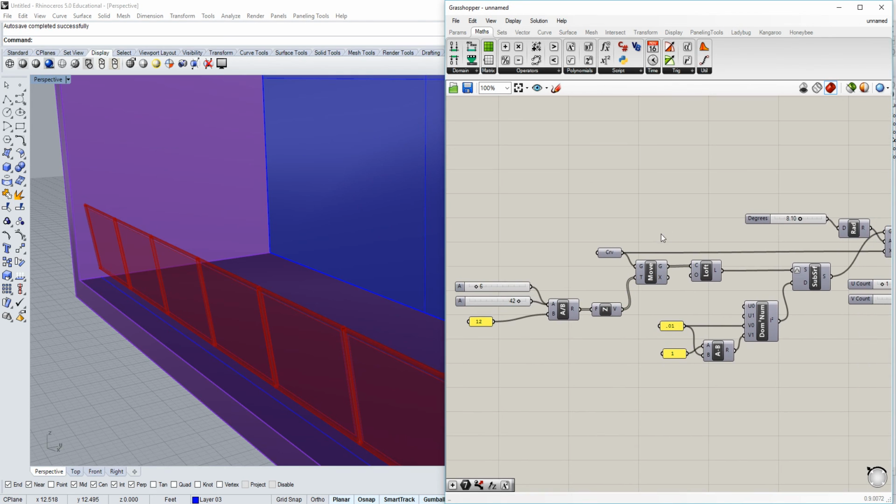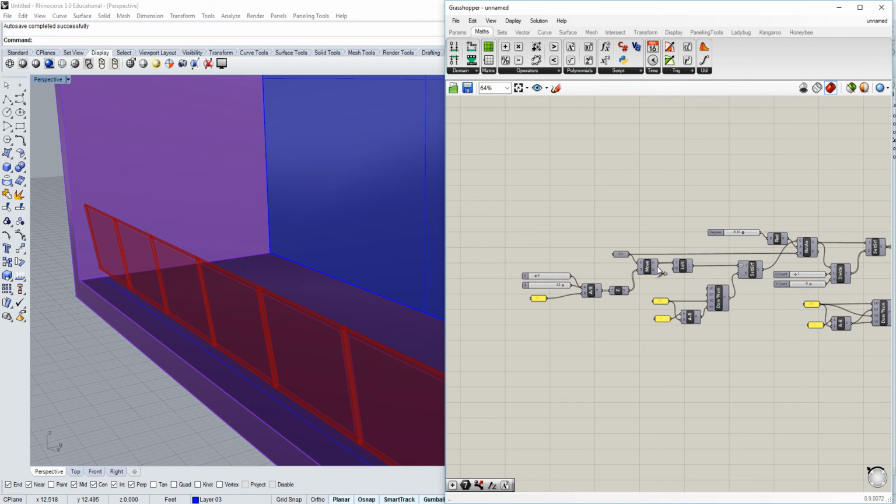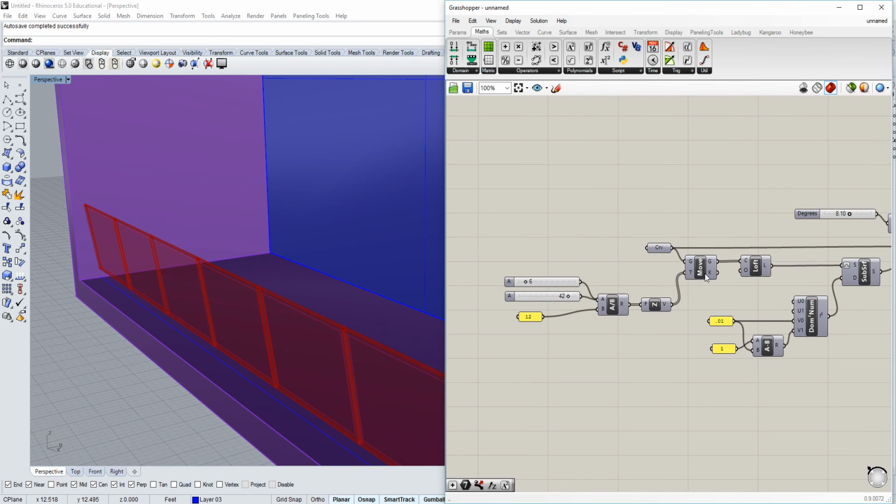Move curve. Okay, so we can basically offset another curve, except this time we're going to use move, and we're going to use the vectors, except we're going to have to do it on the side. So I'll pull this one above. Let's see, we'll go grab that, this, and this. I'll pull this one above the curve so that we kind of have two offshoots here. So we got one move and another move. Turn these on so you can see them again. Those are the originals. This is my new set, except I'm going to get rid of one connection and change the value to 36 inches.